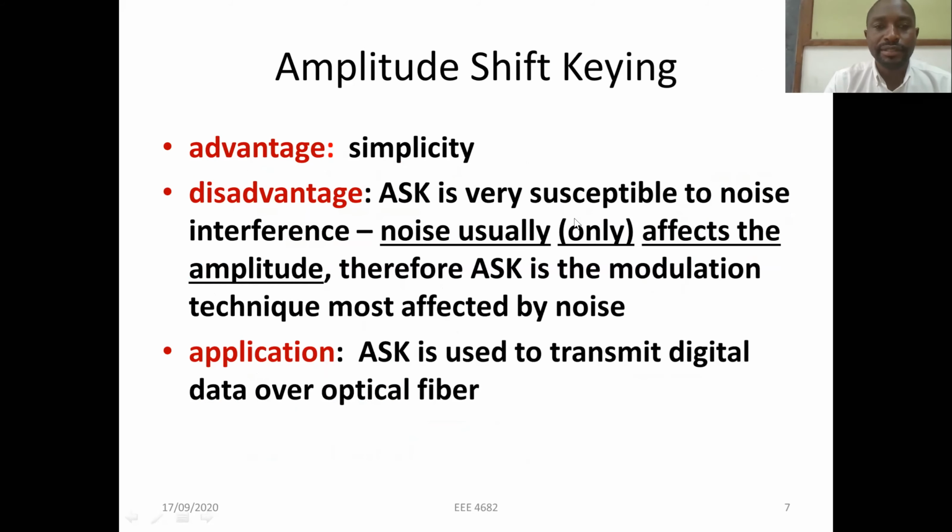Under frequency shift keying, basically what you're doing is to keep the amplitude and the phase of the signal, but you'll be varying the frequencies. Therefore, in a practical system, you will have 2 carrier signals denoted by F1 and F2, and they will be in such a way that whenever you have a binary input of 0, the signal will take the frequency of F2. Whenever you have a binary input of 1, it will take the frequency of the first carrier signal F1.